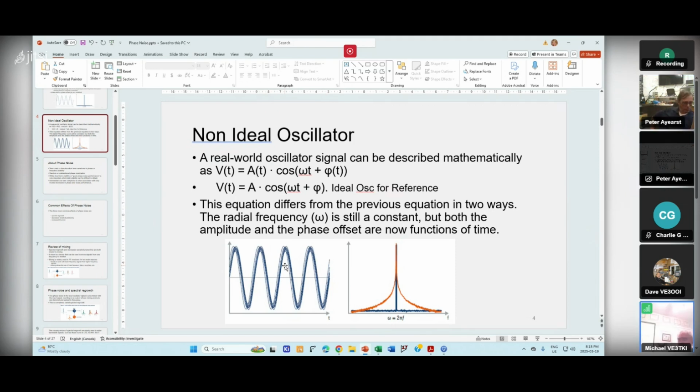Yeah. You can also turn on averaging on your scope, and that acts as a low pass filter, so it'll filter out some of the noise. So then you'll get a much cleaner signal. I use that all the time. I average almost everything to try and get rid of the inherent systemic noise. Like if your signal's got noise, averaging might fix that, right?